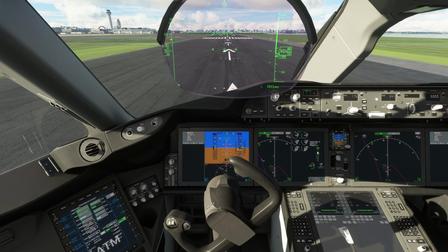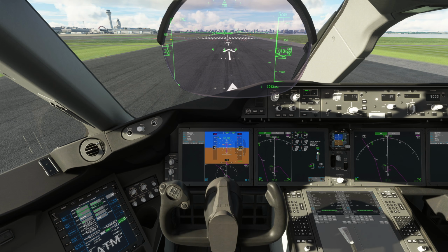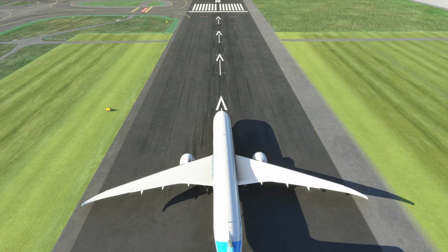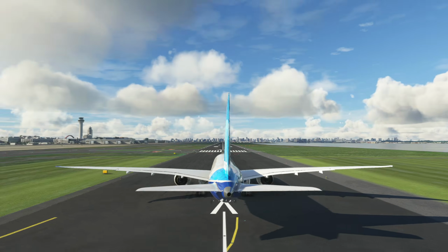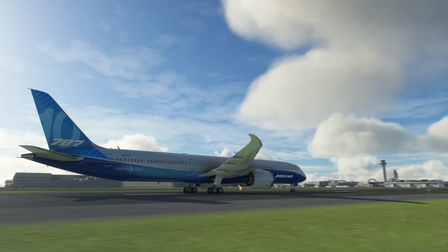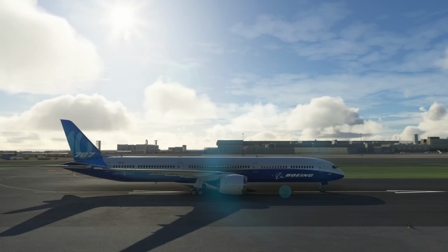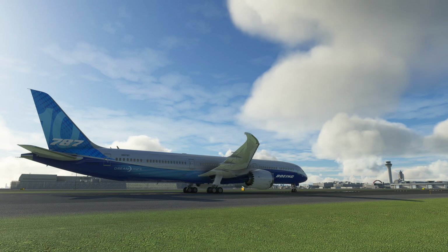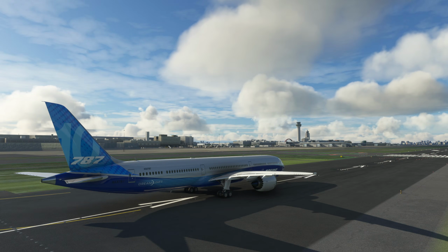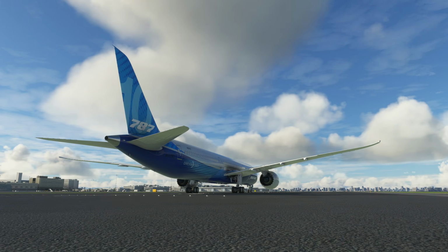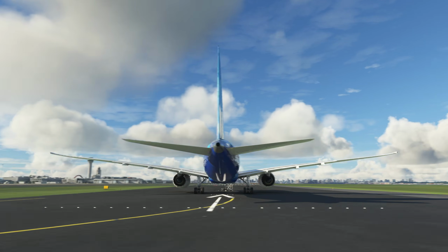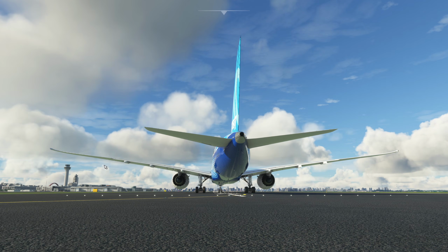And you can end up with some rather extreme looking yoke positions on the 787 to keep it wings level. The reason for this is that the wings are very high up on the 787. They are remarkably high actually. The airplane's quite low on the ground, but the wingtips come up to almost where the 777's wingtips do. It's also prone, therefore, to, as it takes off, the wings start to flex more and more up.